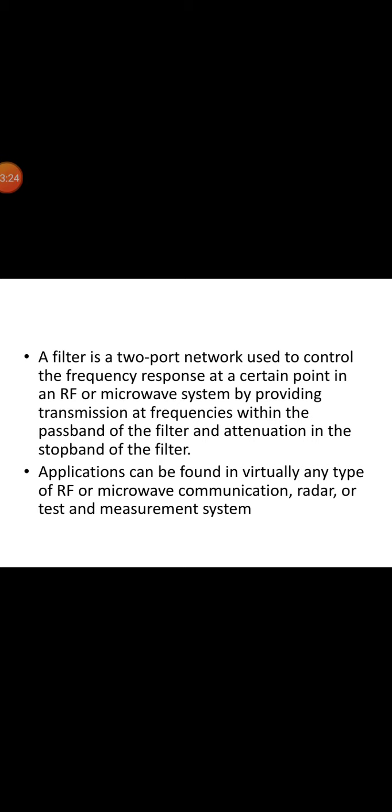And now let us discuss the periodic structure of filters. An infinite transmission line or waveguide periodically loaded with reactive elements is an example of a periodic structure. A periodic structure can take various forms depending upon the transmission line media being used. Often the loading elements are formed as discontinuities in the line itself, but in any case they may be modeled as lumped reactances in shunt on a transmission line. Periodic structures support slow wave propagation and have passband and stopband characteristics similar to those of filters. They find applications in traveling wave tubes, masers, phase shifters, and antennas.